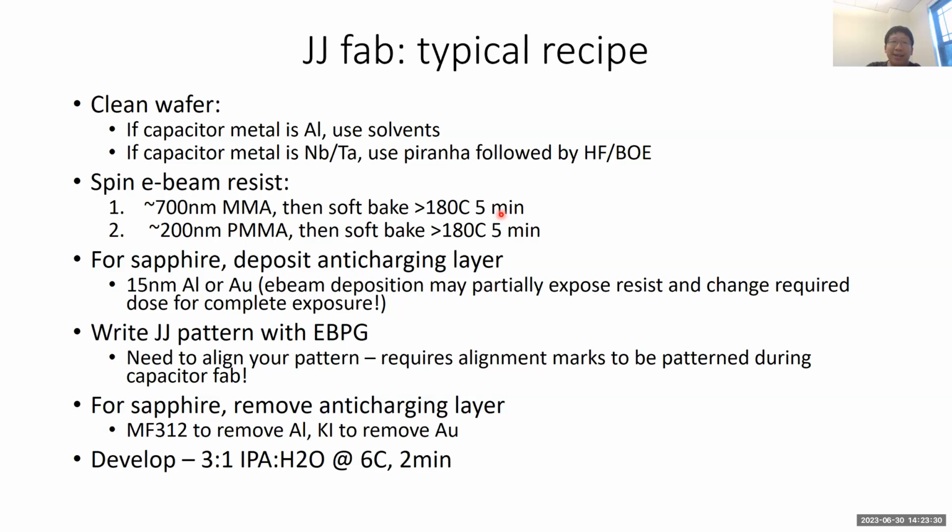So why do you use static oxidation over plasma oxidation? Great question. The most blunt answer I can give is because that's what works. There's a reason why everyone uses aluminum oxide, aluminum junctions, and there's a reason why everyone does static oxidation. It's the tried and true method for the past 15 years now, I think. It's what's always consistently produced good quality junctions.